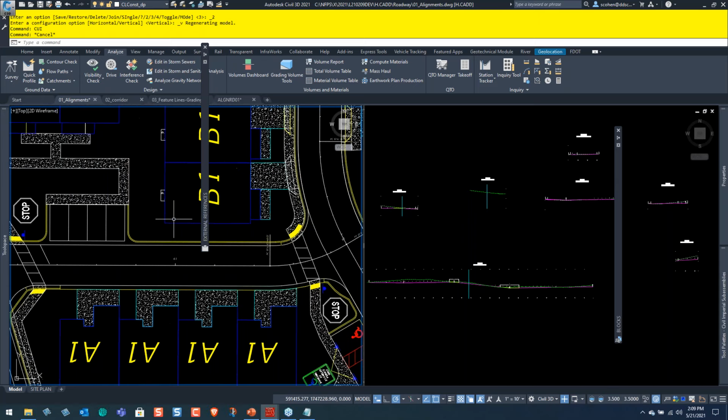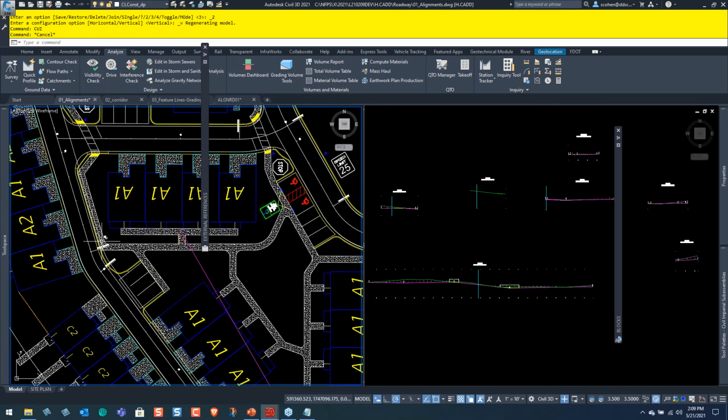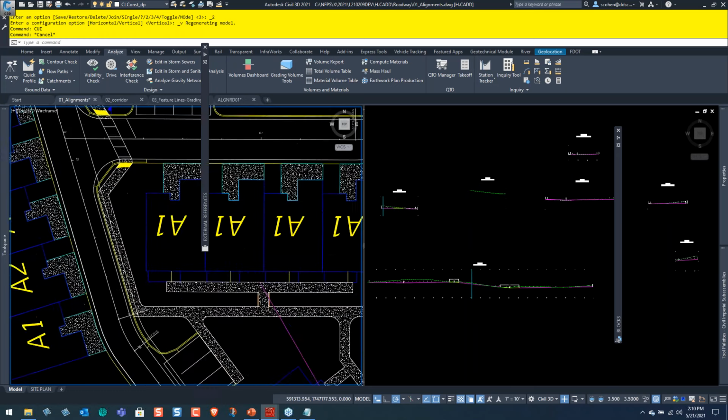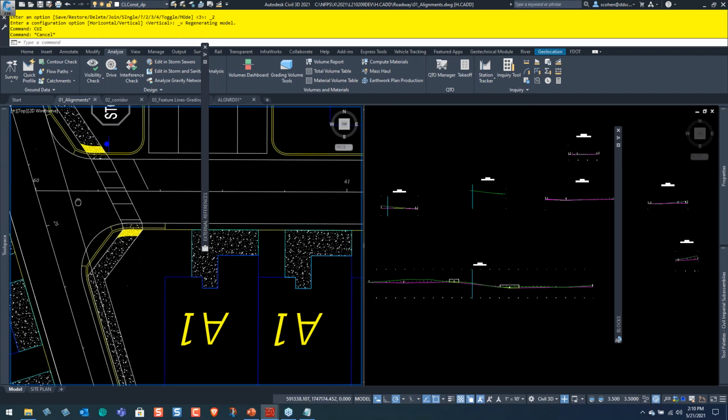So let's go ahead and actually create the profile for this road, because the tip I want to show you here is one of the key things. As you can imagine, I've got this main road here and I've got this main road here. Well, as I design the profiles, as I go in and say, okay, I need to lower this here because I'm getting too steep of a grade, or I need to raise it because I'm getting too steep of a grade, whatever it is, you need to figure out the buildings and tie-ins. You want all of this to talk to each other, right? It's a pain in the butt if I actually have to figure out the elevation here, then adjust it in this location. There are ways to do it. There are ways to trick it with labels, but there's a much more automated way.